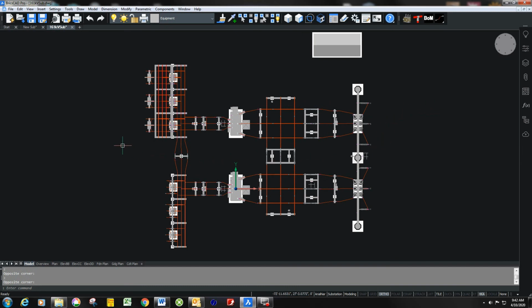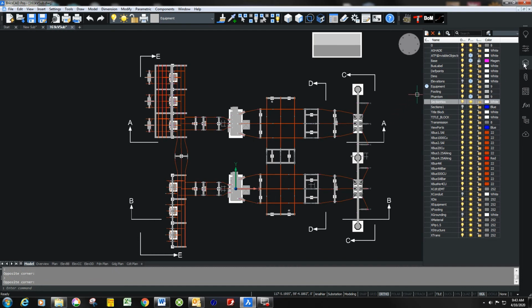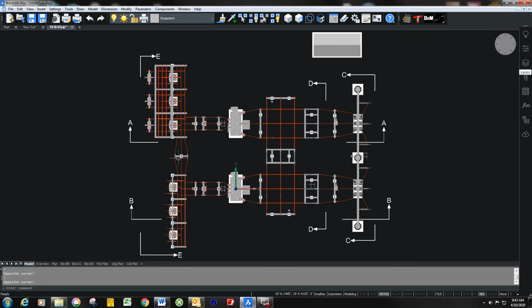Now, once you've defined your plan view, the next thing you want to do is determine the sections or elevations, and I'll probably use those terms interchangeably. The elevations that you want to create demonstrate to the substation packager or the contractor exactly how you want this substation to look. So I have actually come in here and defined some section lines in nice big letters and lines so you can see them. This is probably what I would call a minimum that you would need. You could probably use some more.